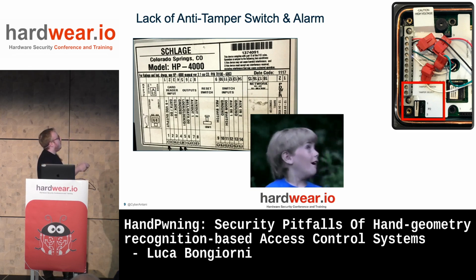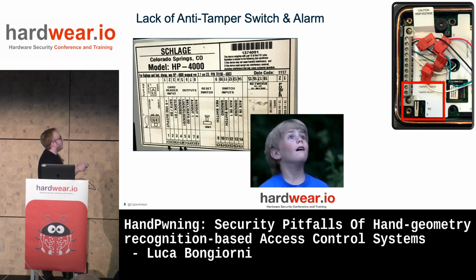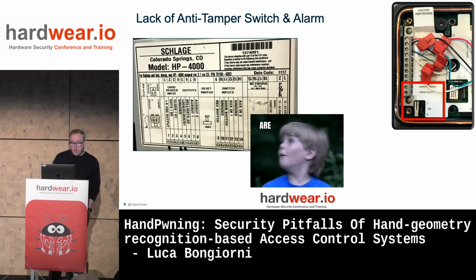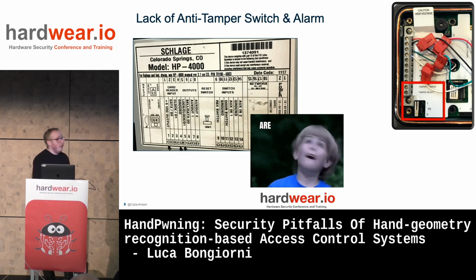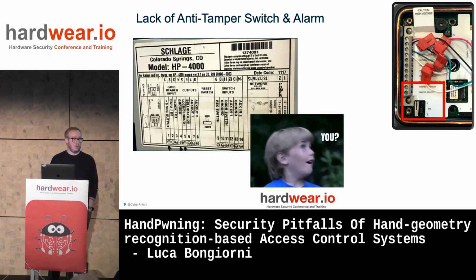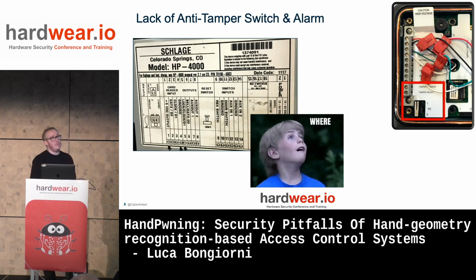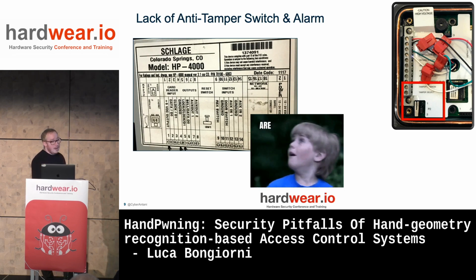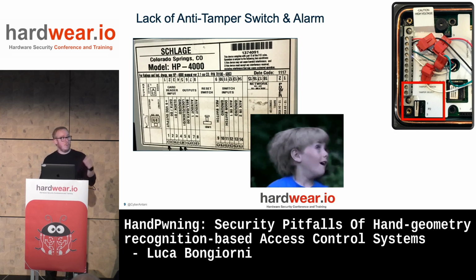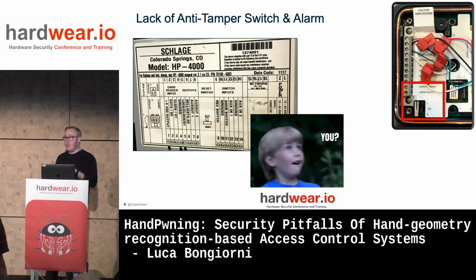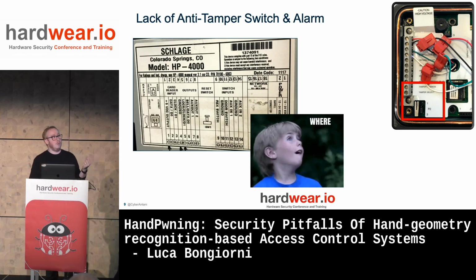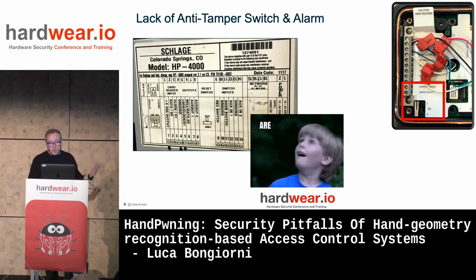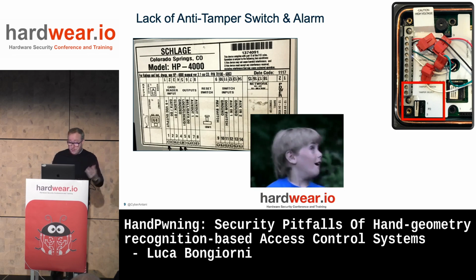So, just going back to this device, as you can see, there is no mention anywhere of any anti-tamper device. So I tried to check deeper on the motherboard, and effectively there was no anti-tamper switch. This is already a failure for this kind of device that is also used as a physical access control system. So anytime you open one of these devices with the master lock, there will not be an alarm triggered remotely to the security guard's room. So you can eventually tamper, you can do things, right?